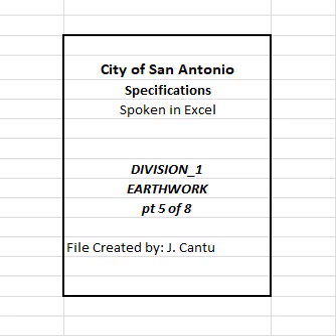In areas of salvaged topsoil, payment for embankment will be made in accordance with TxDOT Item 160, Topsoil. Shrinkage or swell factors will not be considered in determining the calculated quantities. B. Original. The cubic yard will be measured in its original and natural position using the average end area method. C. Vehicle. The cubic yard will be measured in vehicles at the point of delivery.